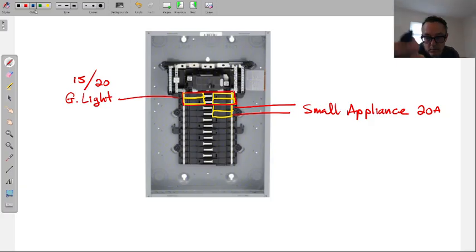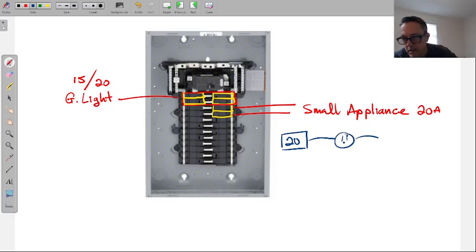So if you have 2 breakers, right? And here it's going to be a little deeper than we need to get into right now. But if I have a 20 amp breaker, and these outlets are going to go into the kitchen for small appliances. First of all, they have to be GFCI, as we learned yesterday. 1 outlet in the kitchen, 2 outlets in the kitchen, 3. Here's the thing about small appliances. They're not low amperage things.